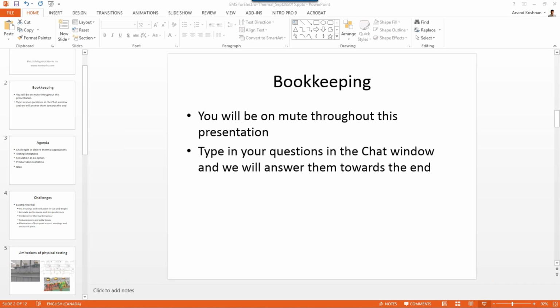Third, simulation helps you to visualize the temperature field, the temperature distribution across a model. You can look at temperatures inside a model, at the periphery, and so on. Whereas if you were to place sensors, you're pretty much limited to having sensors at the outside of the exposed surfaces. Sensors inside the model can be done, but it's highly impractical. And most of the hotspots could actually be in the interior.